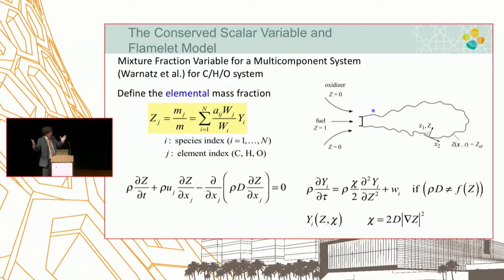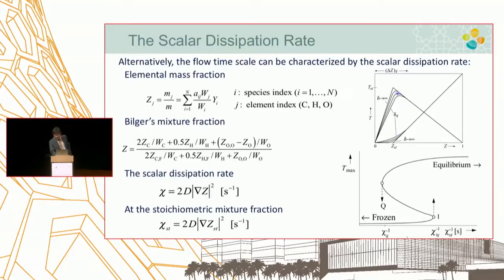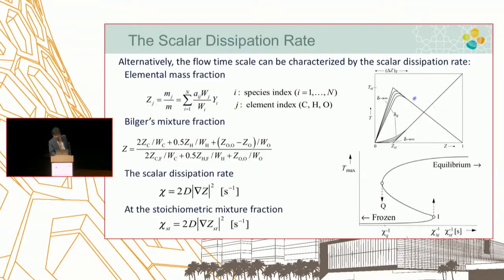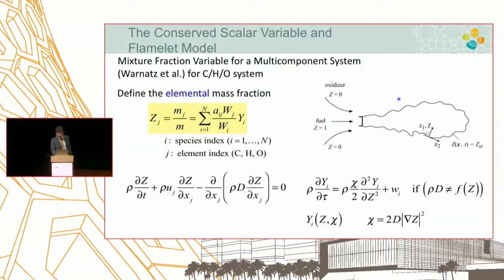You cannot easily overlap them. However, if you use the mixture fraction, which is defined as 0 in the oxidizer and 1 on the fuel side, then on that coordinate system everything falls back together because Z scales to 0 to 1. And it looks just like that. So every cross cut you have will fall back on this single curve. Whether it will be close to that or that depends on the local strain rate, which is called the scalar dissipation rate right here. So this is a prelude to the general framework of the Flamelet approach.